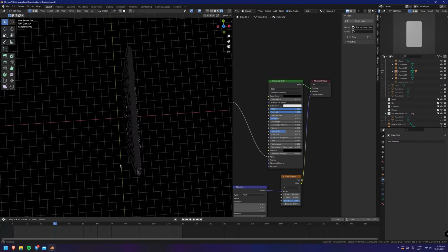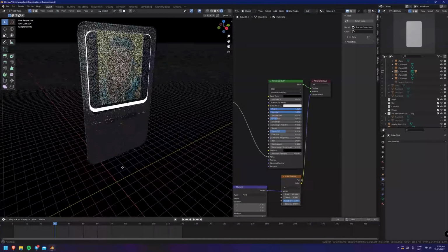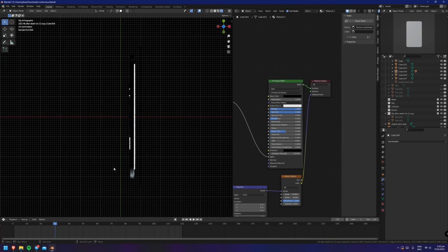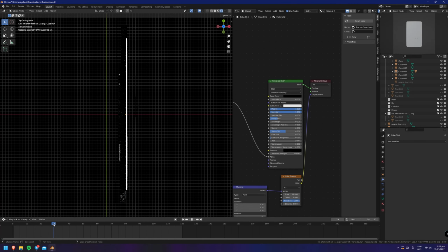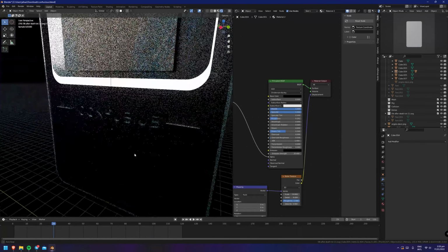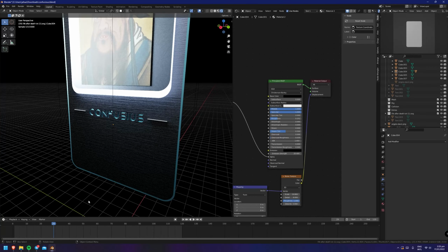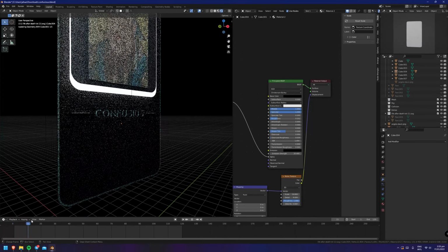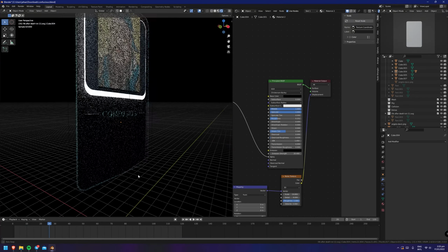And a helpful tip that I've realized while I'm working on this is, if you press 7 and go into the top view, the positioning in which it is the easiest to work with is around frame 30, where it's completely straight, because you'll notice that if you import the text, everything is aligned on the grid. So it's best practice to only move it 90 degrees at a time in whichever way you want. But once you burn it in, then it will obviously move with the mesh. Let me know if you have any questions, and yeah, good luck.